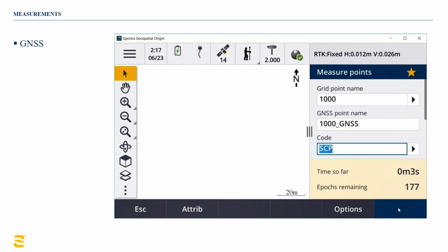So now once this point is measured, I can then apply this northing and easting to this measurement of the latitude and longitude, and I could do a 1-point calibration, which would then assume ground distances and a north rotation.